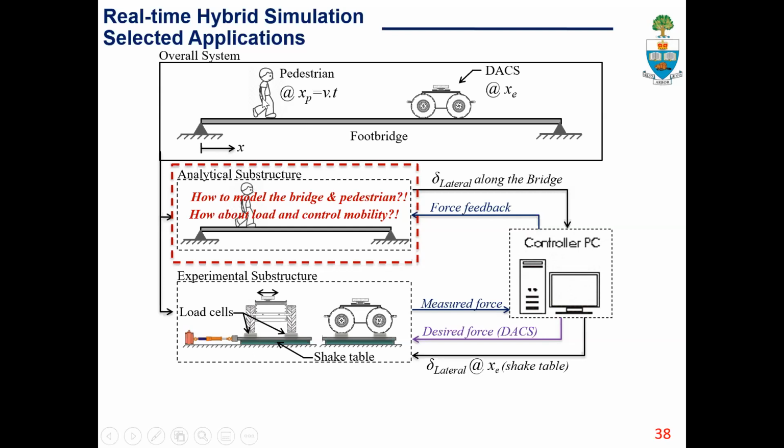In this particular problem, both the loading is moving as well as the control device. So in order to address these, we have recast the dynamic problem in modal domain using state space, and we were able to introduce the mobility of both the load and control device accurately in the formulation. So this required an original formulation of the real-time hybrid simulation problem.